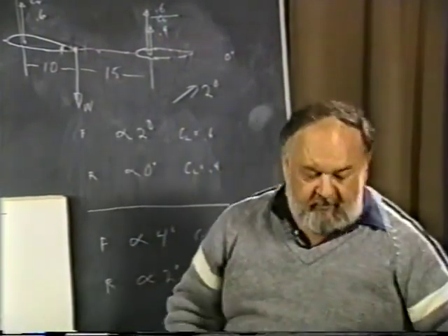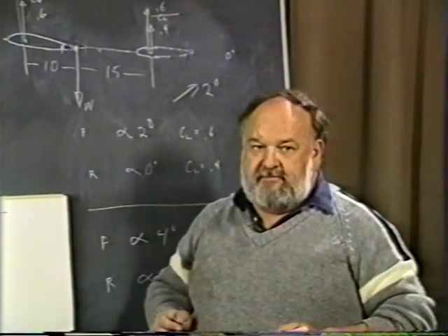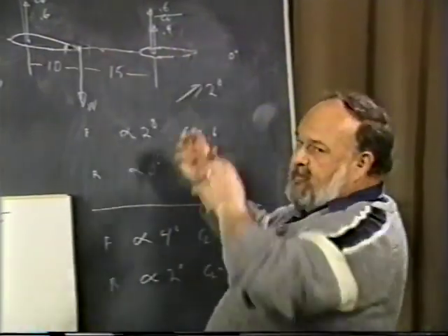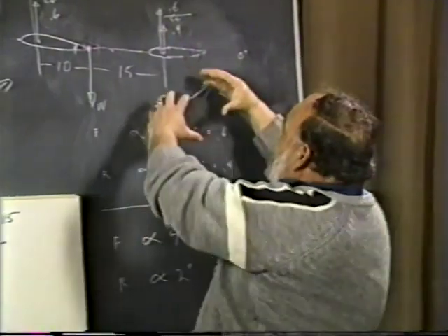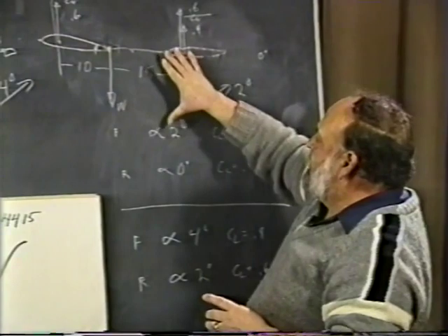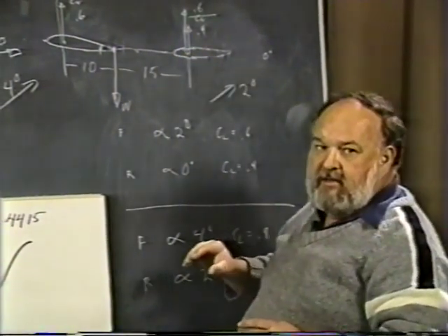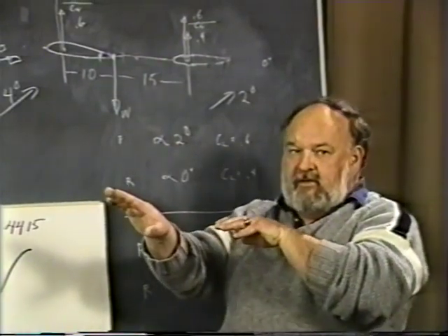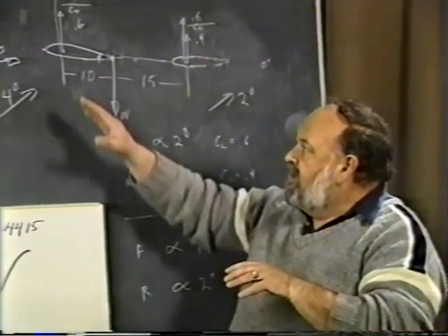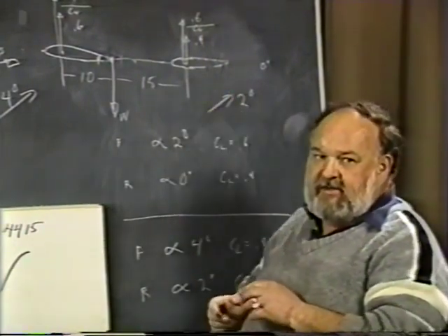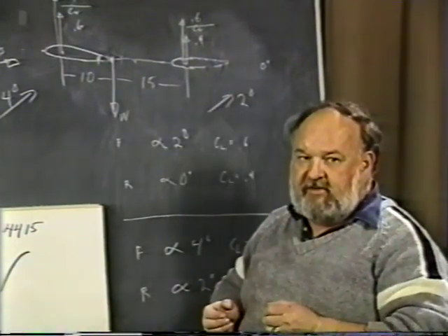Now, if this is a canard airplane, it's all right. You've made this surface smaller and smaller, this one bigger and bigger. Your total lift on this one is very large, so therefore your balance point, your center of gravity, has to keep moving further and further back. But the same fundamental things must exist. When you're flying along and a gust hits you, this will increase in lift, this will increase in lift, but this one has to increase in a greater percentage of lift than the front one.